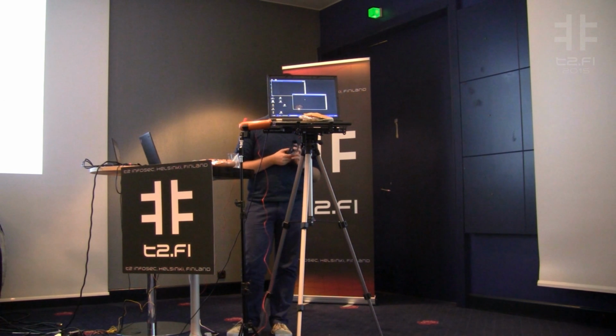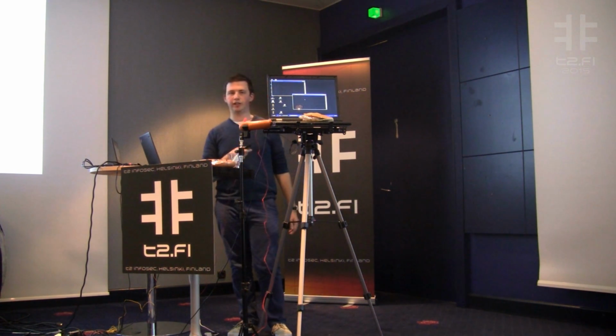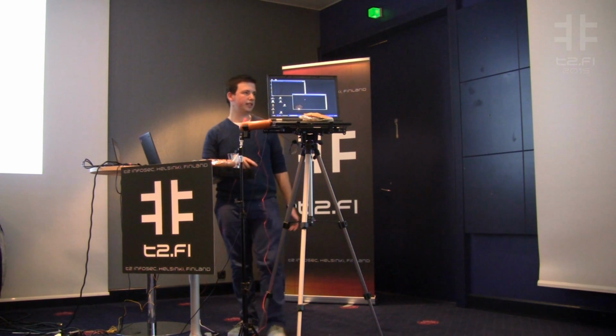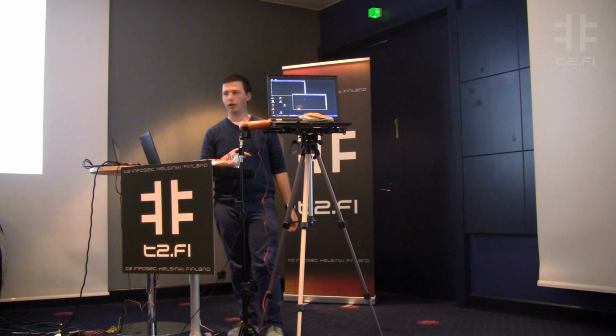Doing this for all the bits of the secret prime key, I'm going to extract the secret prime key. For RSA 4096, this means around 2048 decryptions, and to do so many decryptions, I need around 1 hour of measurement.